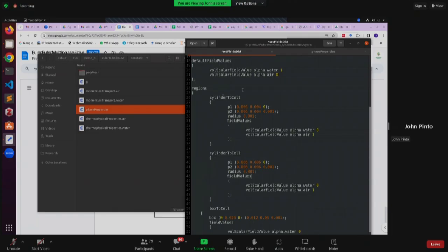We had to copy this command so that it is done twice. At the top it will create one bubble, at the bottom another. So just these two changes: the X coordinate will remain the same, the Y coordinates will be different, with a radius of 1. I think I need to reduce this because 4 plus 1 and 6 would have them touching otherwise. Let me make this 3.